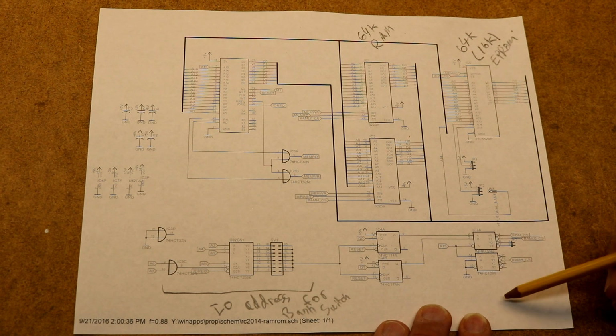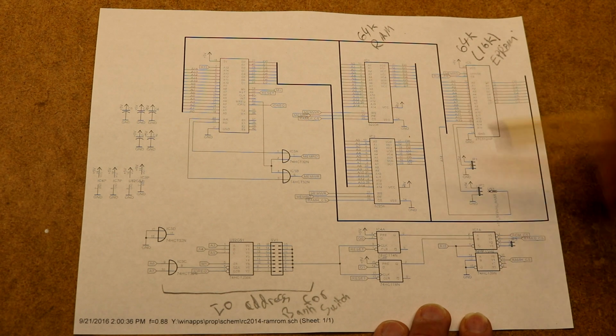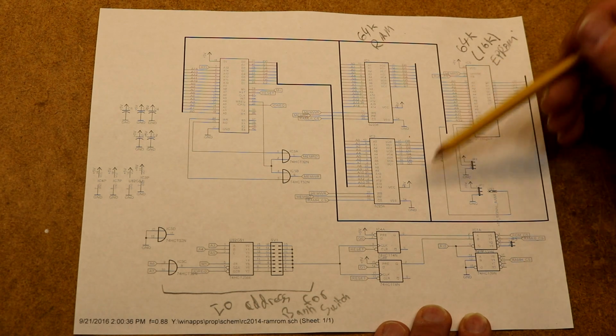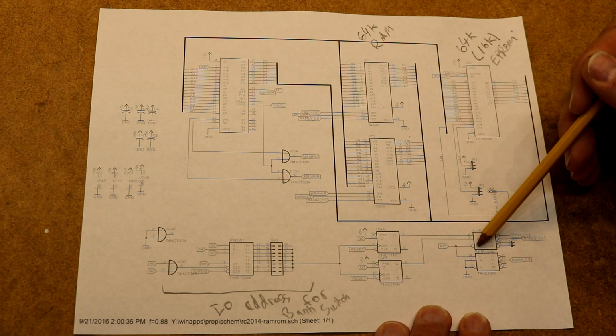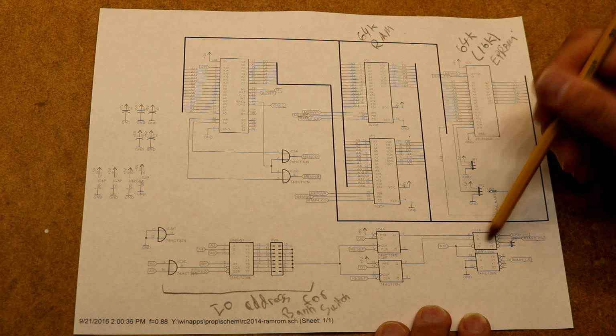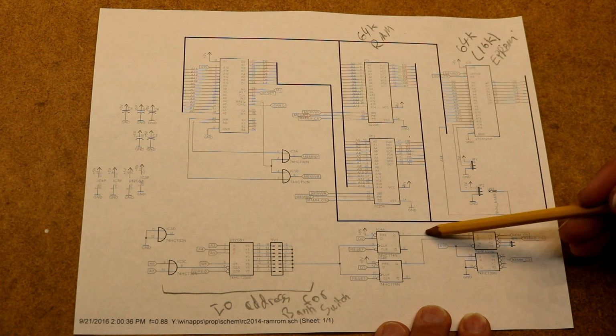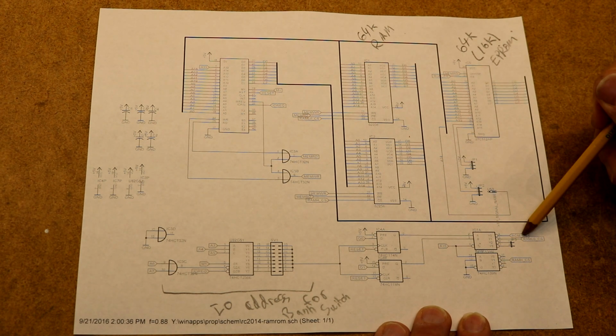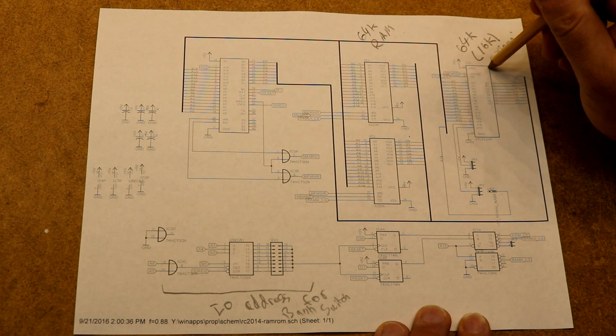And then over here is a 2 to 4 decoder. So the output of the flip-flops will form the selection of which output to drive on the 2 to 4 decoder. And then our A15 also comes down here and enables the 2 to 4 decoder. So when A15 is low, this decoder will be enabled, and if these 2 bits going into it are 0, 0, then it will make this ROM CS first output here low, which will enable our EEPROM.